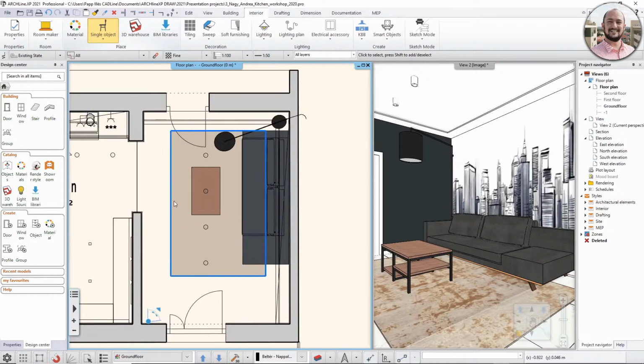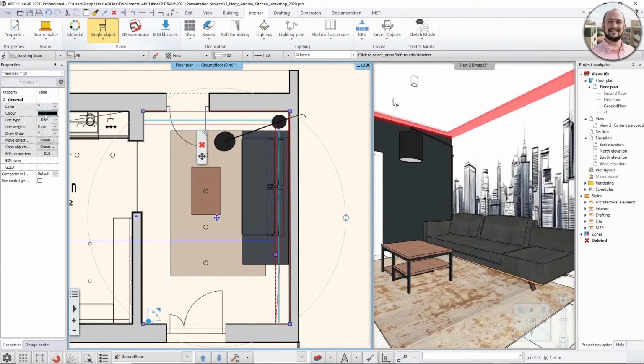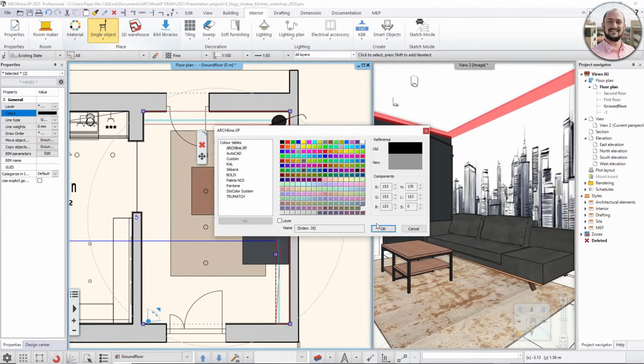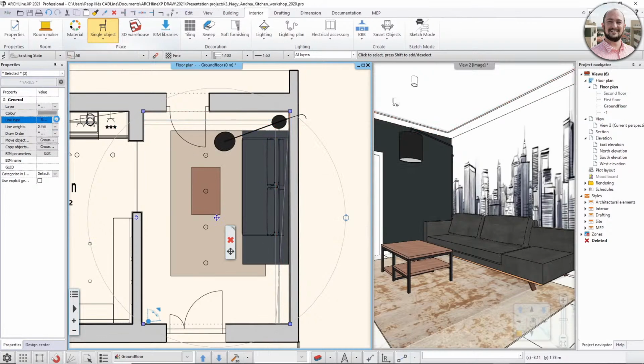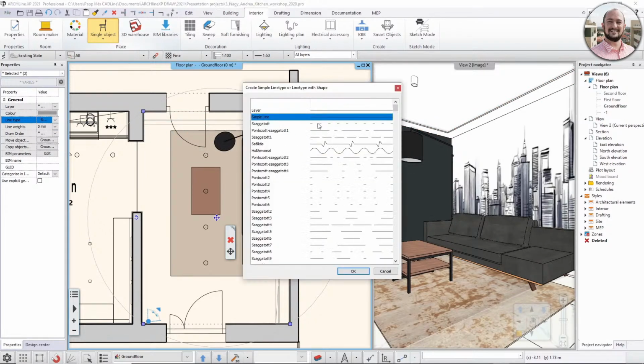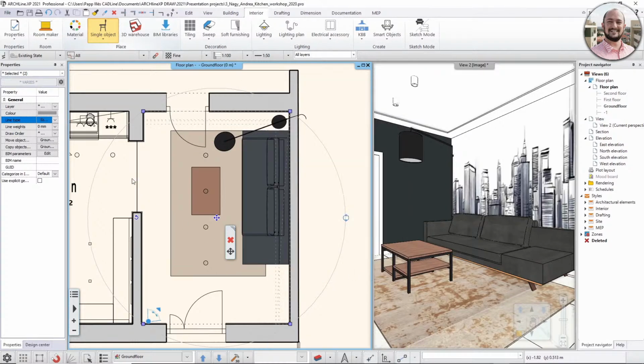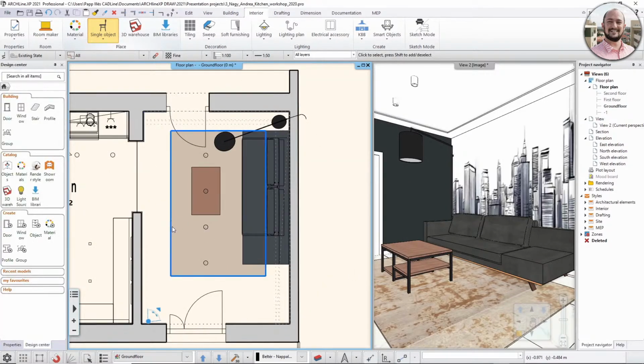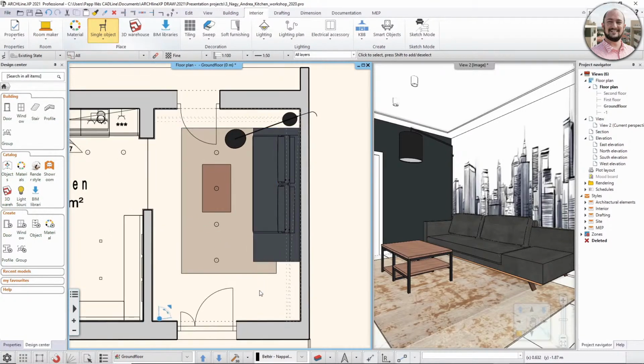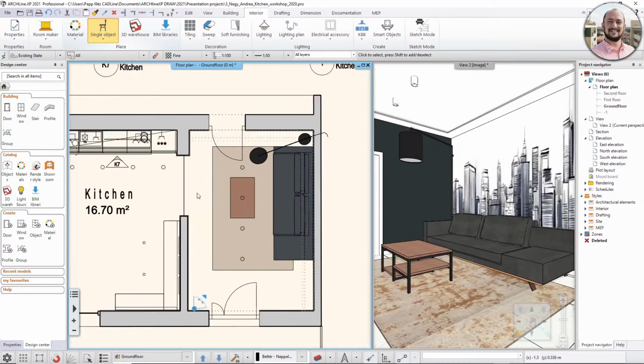It is a very simple and very powerful tool to organize your drawing and make it easier to read for your clients and for yourself, also by extending this with other things, like for example, let me just change the color of these supporting parts and use, for example, a dash line here, and then hit OK. And then now my drawing, with a few clicks and using the 2D fills and the drawing orders, is much easier to read and much easier to understand, and this is what I will publish in the final drawing. So this is how easily you can reorganize the content like I did.